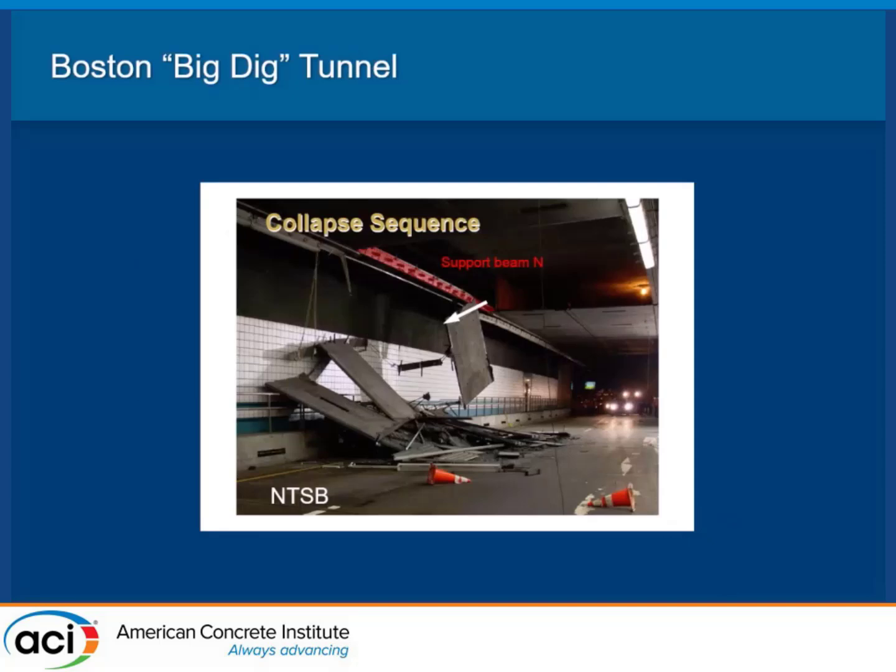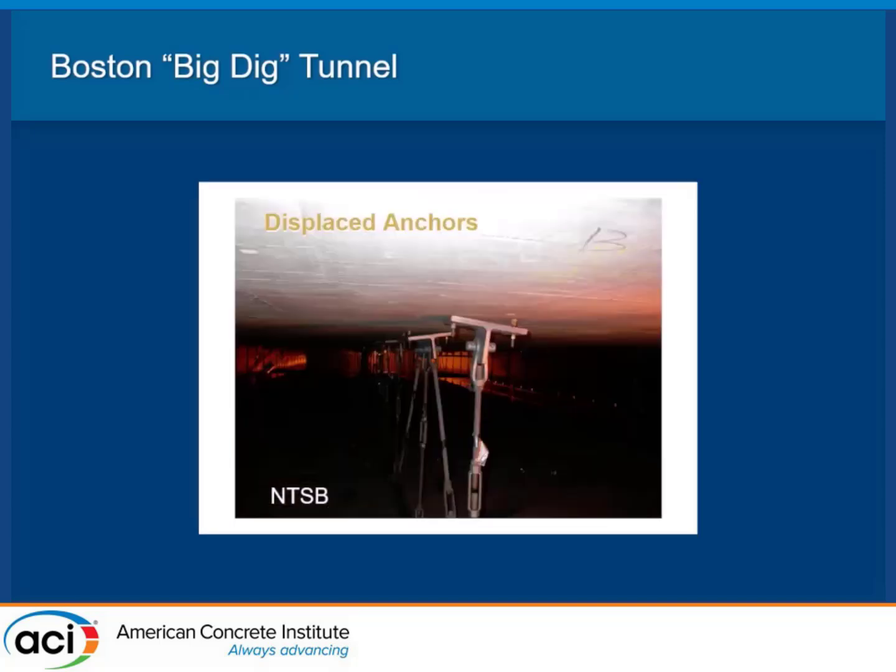And so this is the scene after the collapse. It looked like this for a lot of the panels. The air intake is above the pedestrian walkway. The anchors supporting the end board and end of the exterior panel are the ones that failed. That is the anchors along line M. For those of you around here who know, it was line M. Further investigation of the hanger support system found conditions like these shown here. The collapse occurred in the eastbound lanes. These photos are of the westbound tunnel in the D Street portal.